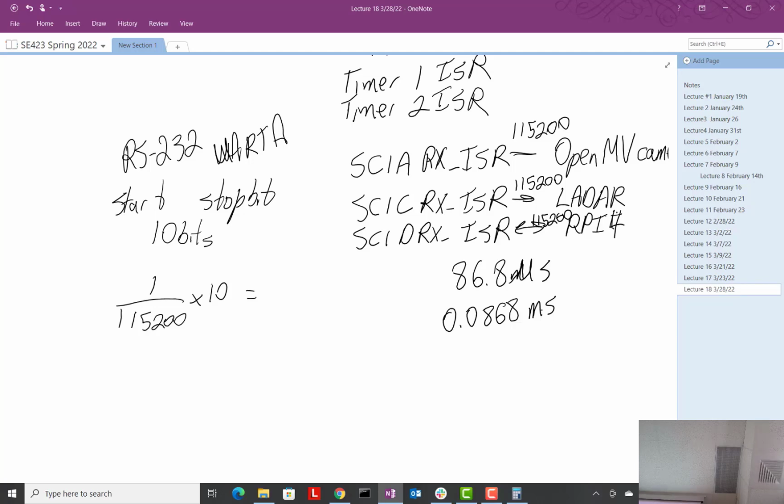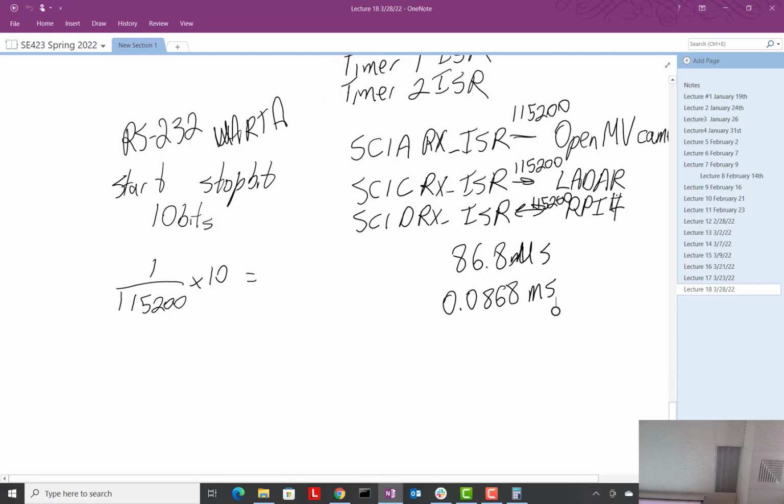So if, for example, a few of you have gotten to timing your software interrupt in exercise 3. Some people got that done. And when you look at the timings, you all will see this. It took about 20 microseconds to do the processing most of the time. But every once in a while, you'll see on the logic analyzer, it skips to about twice as long. So every once in a while, that software interrupt is taking, say, 40 or 50 microseconds to process. And just imagine if we allowed that software interrupt to do that code without being interruptible.